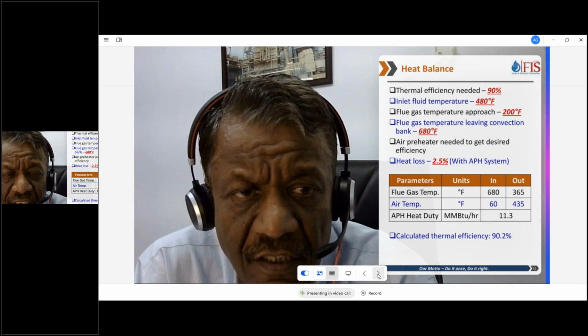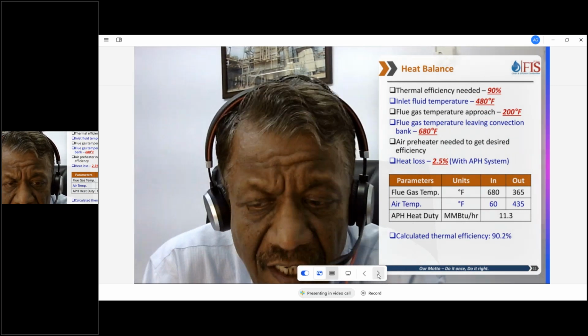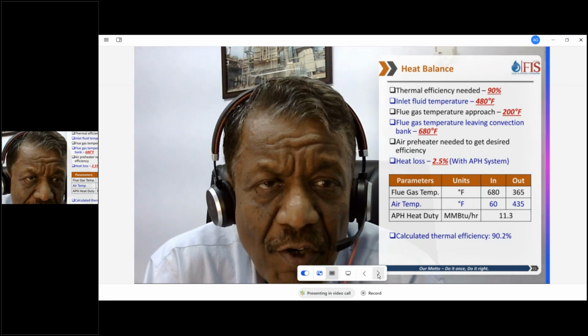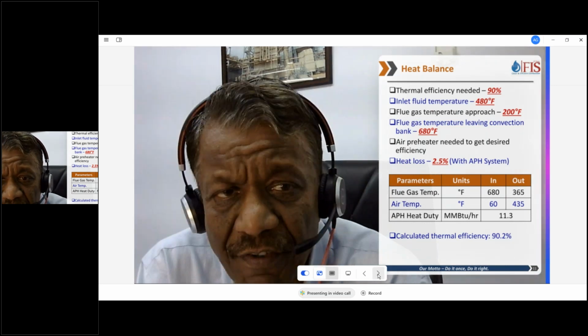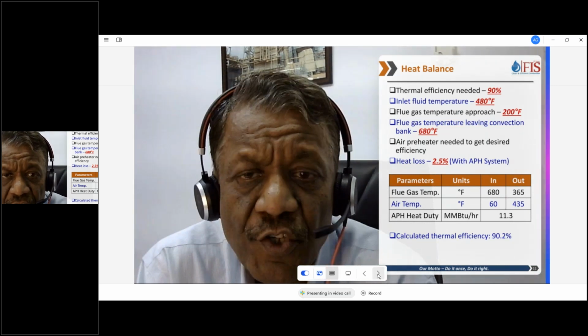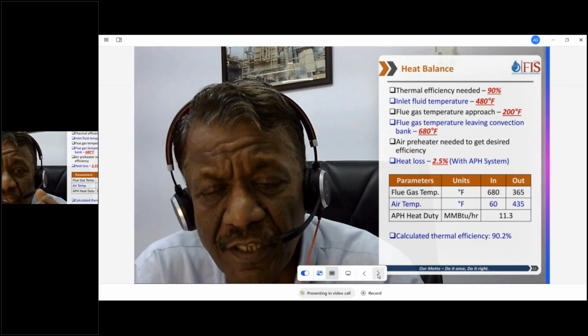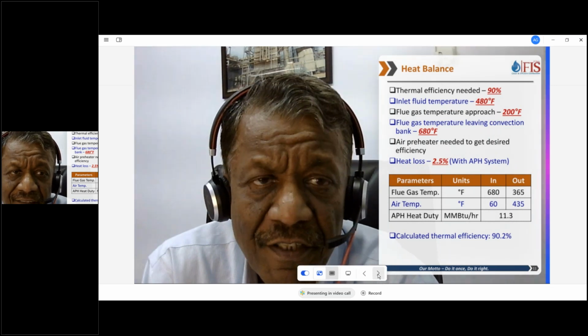So when we did the heat balance in our last webinar, the client wanted an efficiency of about 90%. The inlet fluid temperature is 480. We had different choices of flue gas temperature approach. Flue gas temperature approach means the flue gas leaving the process coils in convection.